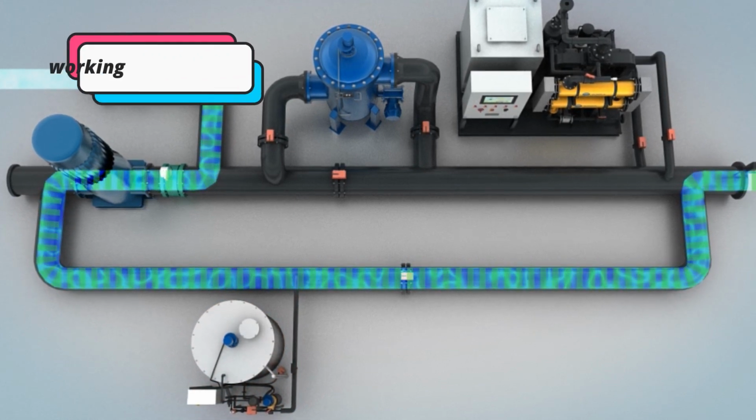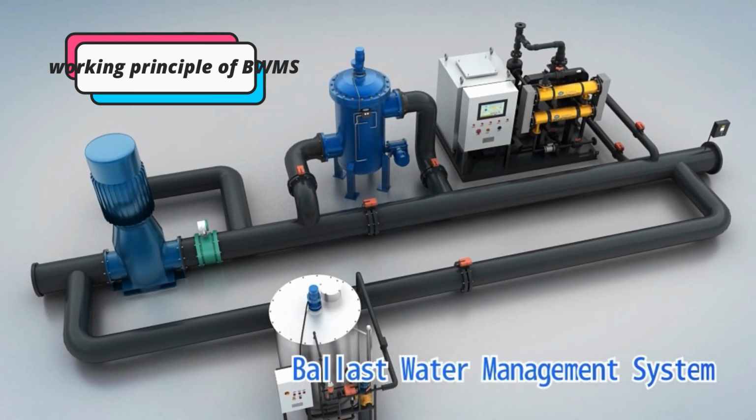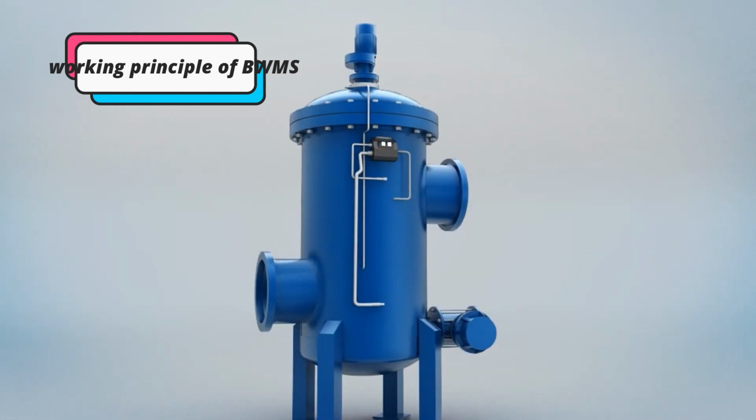If the TRO concentration is lower than 0.1 ppm, ballast water will be discharged to the sea directly and the system will not be operated. There are three major components: water management system, filtration unit, electrolysis unit, and neutralization unit. During the ballasting process, ballast water should flow through an automatic back flusher filter firstly after the ballast pump.